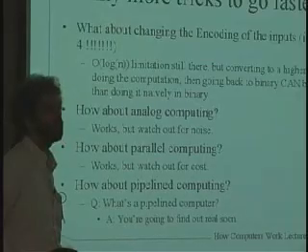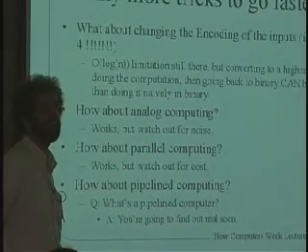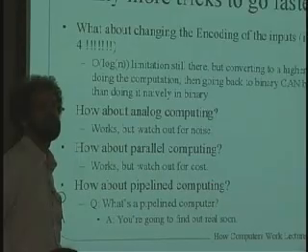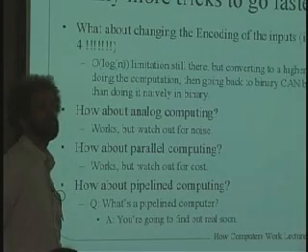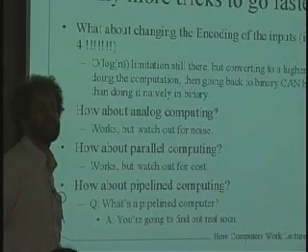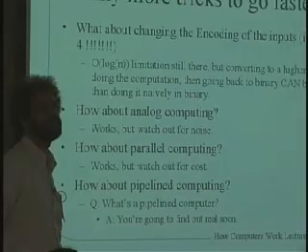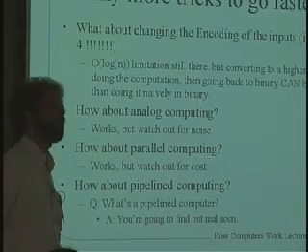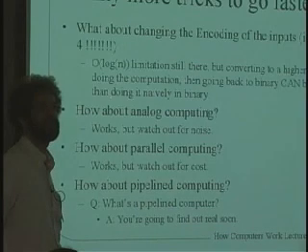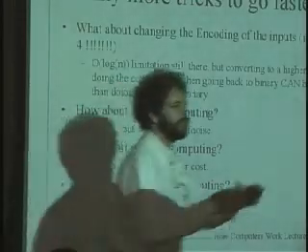And just to give you a hint as to what that is, who said that we had to do all the bits at the same time? In other words, if we thought of the 32 bits of an add as 32 steps in the assembly line of building a car, right? Who says that one guy has to build the whole car, and then when he's done, he has to go back and build the next car? Why can't we have 32 guys, each one engaged in building a particular part of the car, and any given car is spread over the line, so that while it takes one car 32 steps to make it through, the rate at which the cars are produced is 1 every cycle, okay?